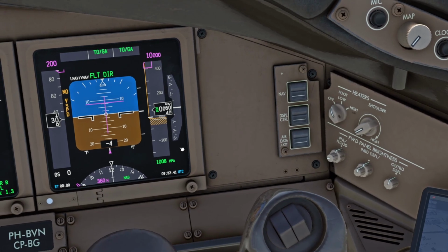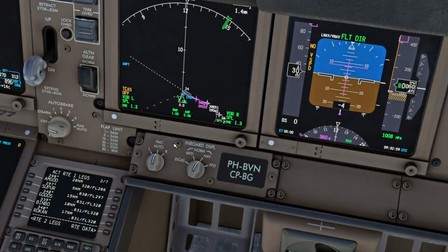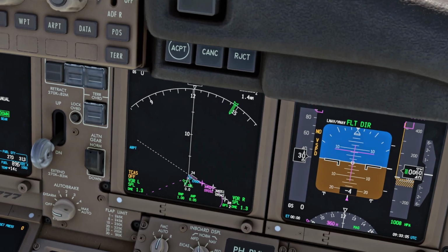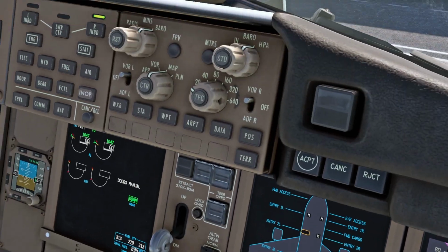In this case, we have a digital clock on this airplane, so we do not have to touch that. Next we have the inboard display selector. It's nice to have that on MFD, multifunction display, so we can use this display for other functions as well. So you can select right inboard here and view, for example, the doors, the status of the doors, things like that.